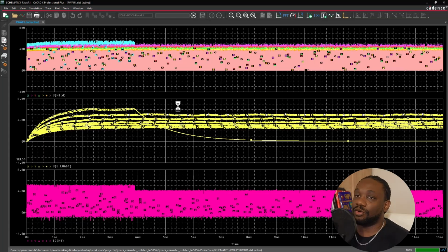So even though I had calculated that 23 milliohms or 20 milliohms or so would be fine, not the case. But because I can run this parametric sweep analysis, I can see that I definitely need to stay at a minimum of 25 milliohms and above for stable output voltage. One little resistor, okay? One little sensing resistor.